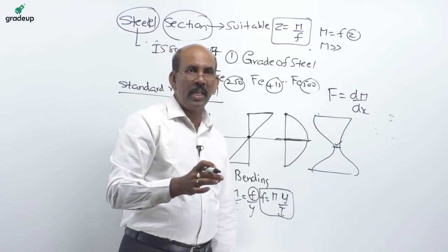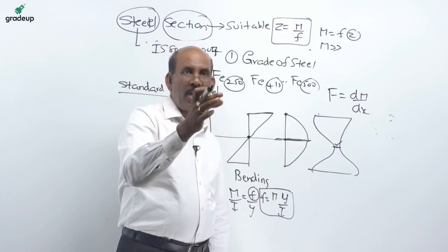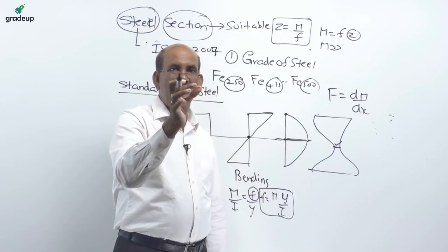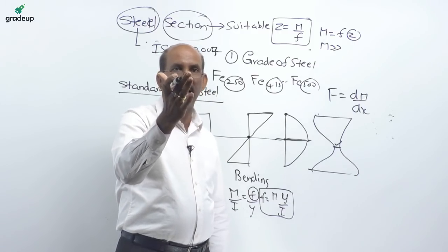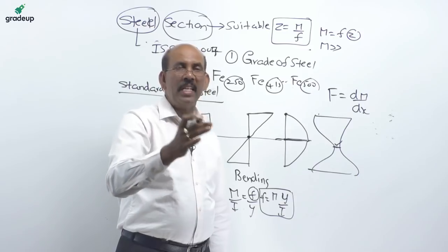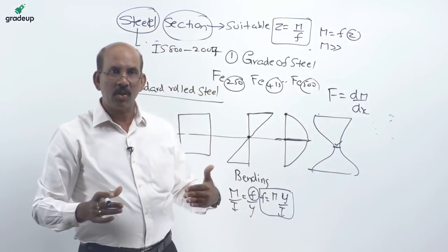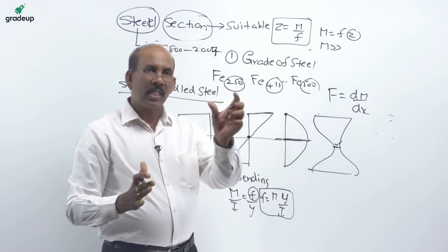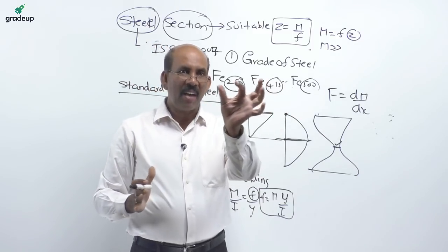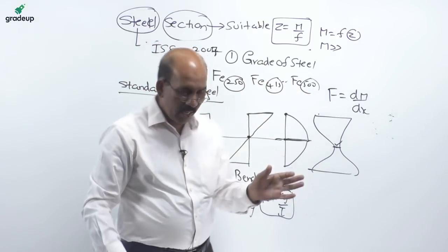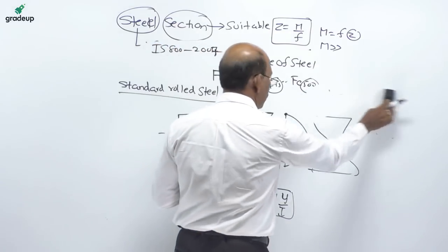Using this, we are going to calculate the stress at this point. Coming to the shear force, draw the Mohr circle, and we will find that diagonal cracking takes place there. That is shear stress with reference to the Mohr circle. The Mohr circle is nothing but a graphical representation of the stresses.